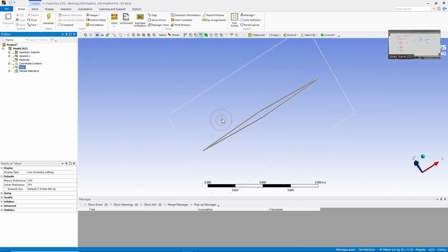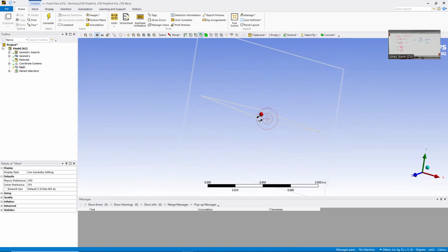And then we want to do a sweep method again because we want to minimize our effort on meshing. Unfortunately, when you do the mesh refinement, it ignores that. If anyone in here is trying to use Fluent for this, I don't know if they do the mesh refinement. I think they do, and then it shouldn't be a problem because you can actually do a literal 2D solution. So maybe this is one I should move to Fluent at some point.